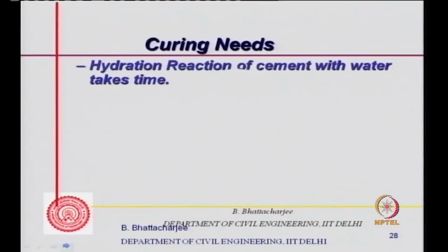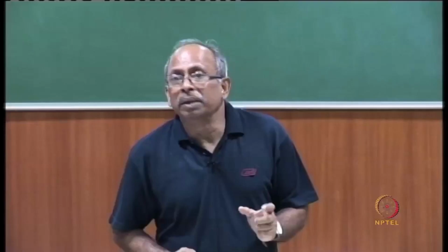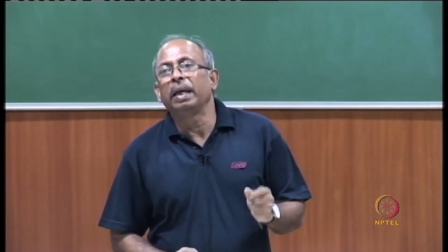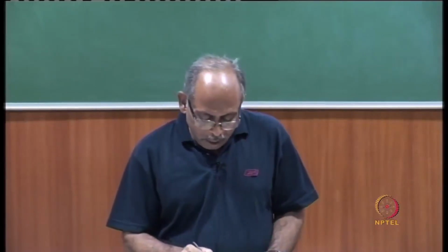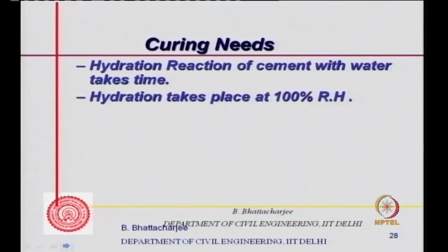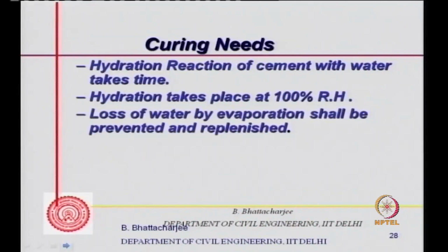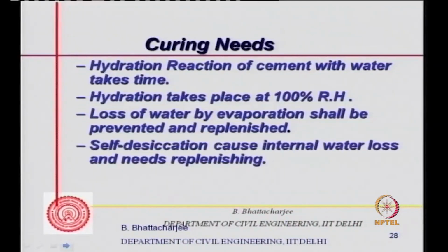Now let's look into the second part of our discussion, that is curing. Hydration reaction is not instantaneous. It's not like an explosion reaction which is instantaneous. It occurs over a long period of time, and therefore water must be available for hydration. For hydration to continue, you need a relative humidity of 100%. Besides, there will be loss of water by evaporation, and it shall be prevented. And if you can't prevent it, it should be replenished.